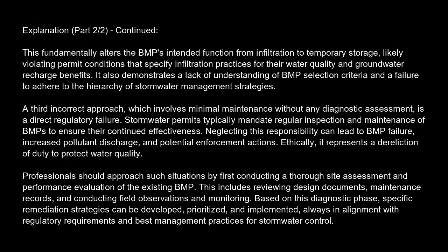Professionals should approach such situations by first conducting a thorough site assessment and performance evaluation of the existing BMP. This includes reviewing design documents, maintenance records, and conducting field observations and monitoring. Based on this diagnostic phase, specific remediation strategies can be developed, prioritized, and implemented, always in alignment with regulatory requirements and best management practices for stormwater control.